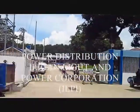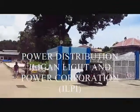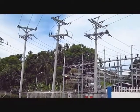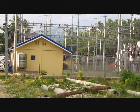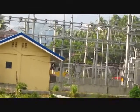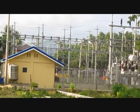Distribution. The distribution system is that part which connects the distribution substations to the consumer service entrance equipment. The primary distribution lines are usually in the range of 4 to 34.5 kilovolts and supply the load in a well-defined geographical area. Some small industrial customers are served directly by the primary feeders. Distribution systems are both overhead and underground.